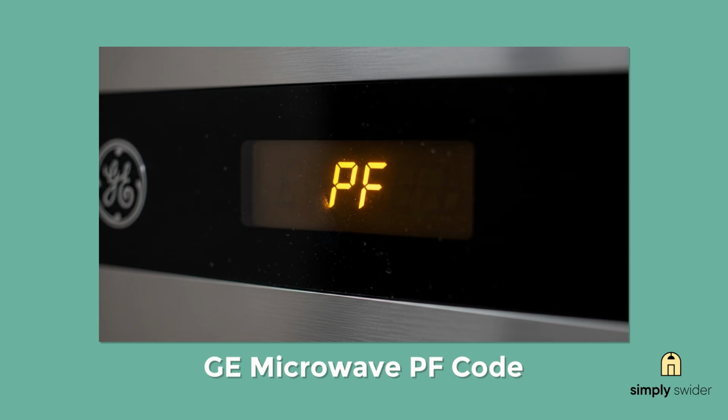That's how you tackle the GE microwave PF code. Start simple with that clear button. Sometimes that's all you need. If the problem persists, work your way through the power supply checks before diving into internal components. Remember, microwaves can be dangerous to work on because of stored electrical charge. So if you're not comfortable with electrical repairs, there's no shame in calling a professional.